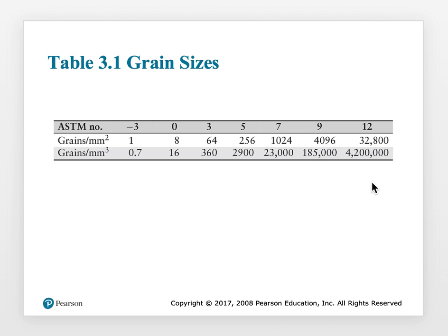But suppose you increase that number of grains to say 10,000. Those grains are all much smaller and finer. So when you start trying to deform that block of metal, those grains will be able to move a certain distance and then get stopped by the next adjacent grain.